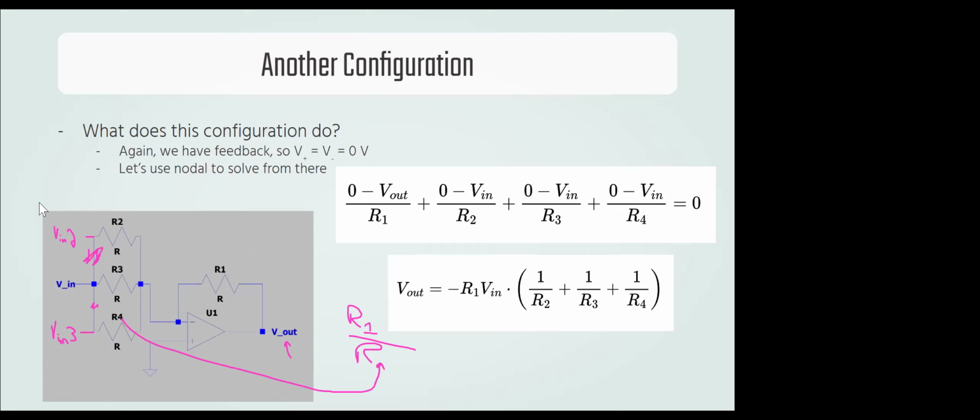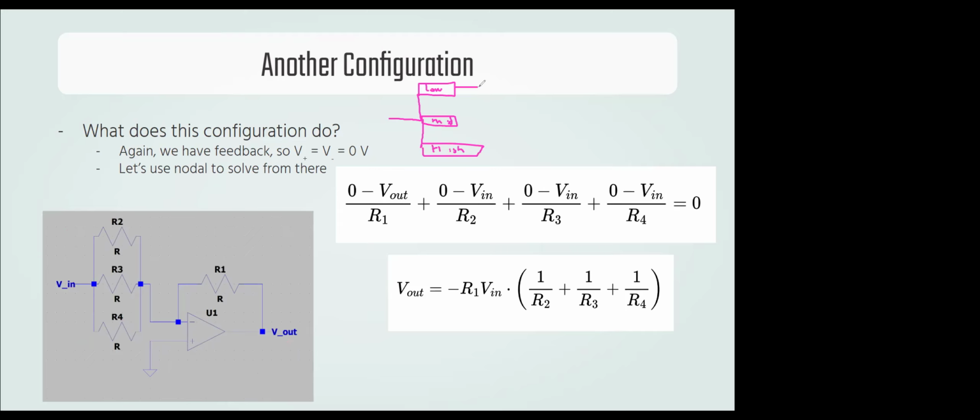And that's a really useful circuit in any application where, for example, say we had a circuit, I don't have it on this computer, but say we had a circuit that, in block diagram form, split some input signal into a low frequency part, a middle frequency part, and a high frequency part, okay? But then we wanted to recombine those, okay? Then we just use a summing amplifier between them. We just put a summing amp.